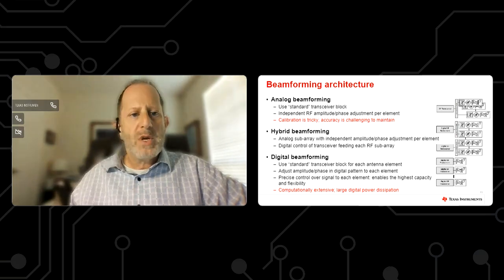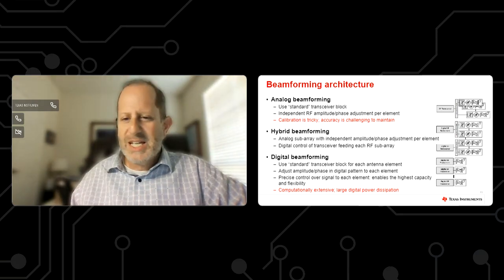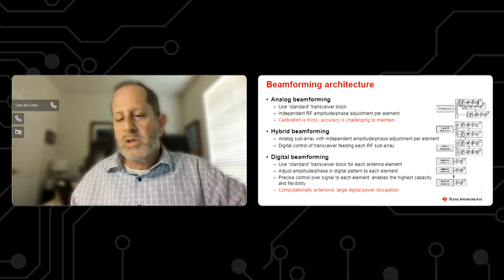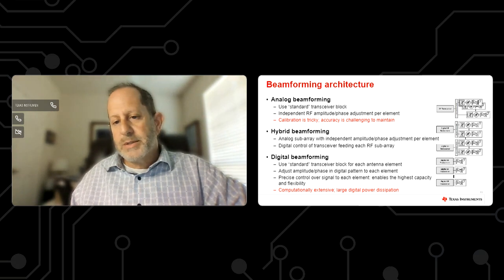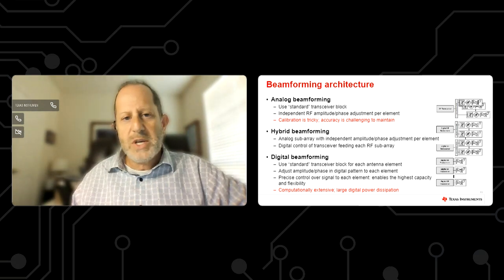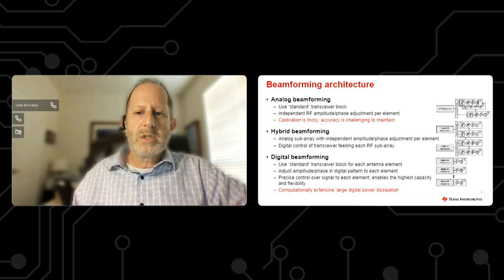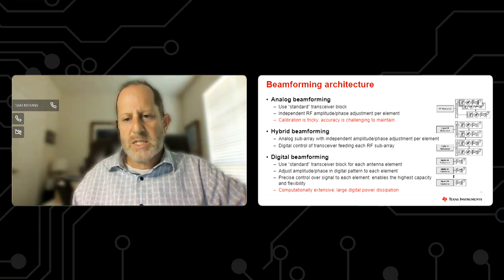So this certainly works, but now we get to the case where calibration gets to be a little tricky. Maintaining your accuracy gets to be a little tricky. You've got a lot of analog components in here that have to be adjusted. Things are going to shift a little bit by temperature. Different devices are going to have slightly different transfer functions and the like. So getting this to maintain across a wide bandwidth, over temperature, over different use cases, that's going to be a tricky endeavor.